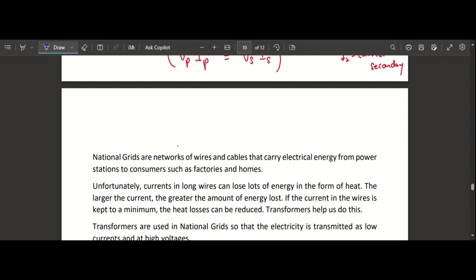Now let's say it's coming from Norochcholai to Colombo. Once it reaches Colombo, let's say it's coming in at 66,000 volts. As soon as it reaches Colombo, it may be reduced to 33,000 or something. Then from the Colombo main electrical supply station, it will be distributed to different sections, right?